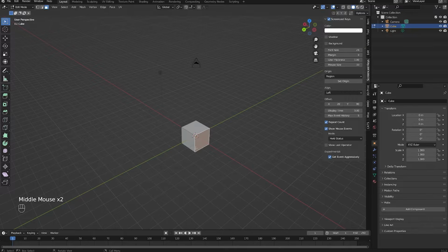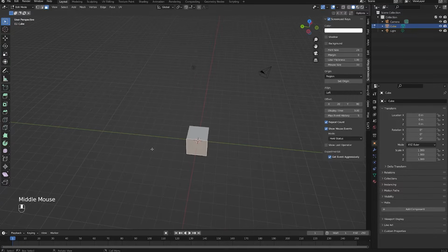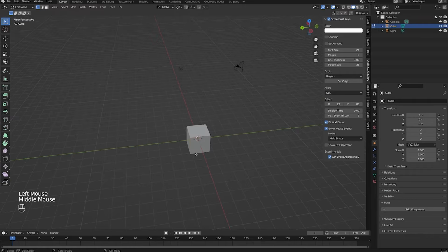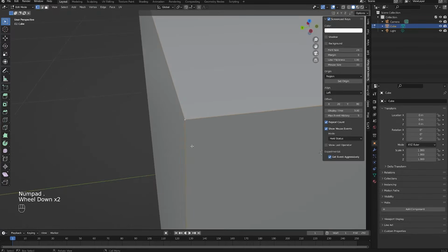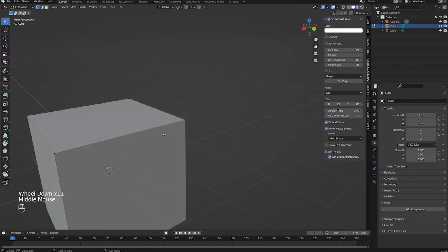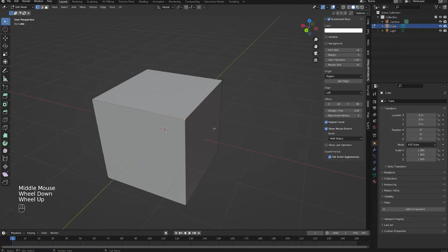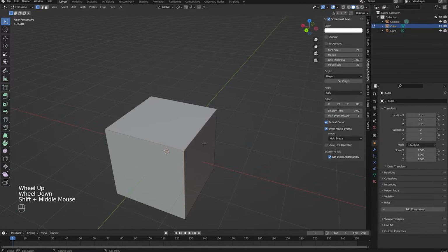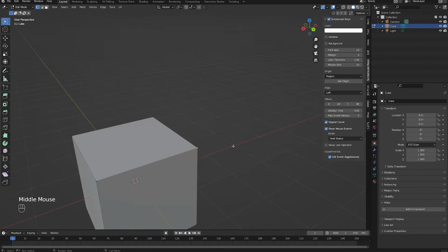And just like in object mode, when we had an object selected, if we press that period delete key to reorient our screen, we can press 1 here, go to vertex select, select something on this object in edit mode, press that period delete key, and it will reorient our camera onto whatever we had selected. So in this case, it's the vertex, so it's reoriented our camera on the vertex. I find that really helpful when I'm moving around, and when I was a beginner in Blender, it was kind of difficult to figure that out.